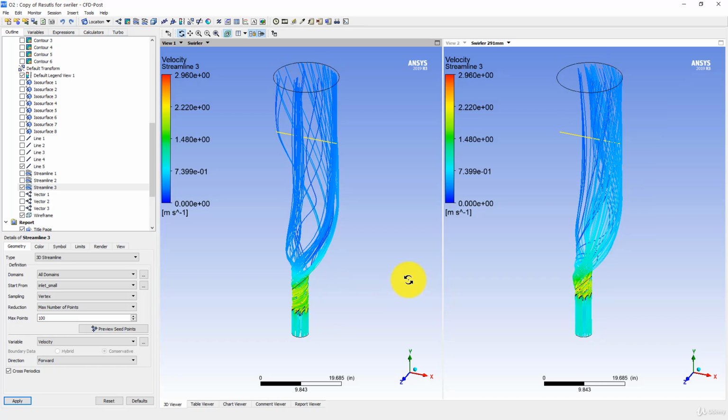But you will notice that what makes things different here in the rest of the workshop is that we started from one figure, that is the figure of that mixing elbow and some boundary conditions, and then we built up the case from the geometry, then making the symmetric model, half model, full model, and making the proper meshing with the inflation layers, and then solving the case in Fluent with the appropriate solver settings, and then analyzing them in Fluent and also in CFD-Post.